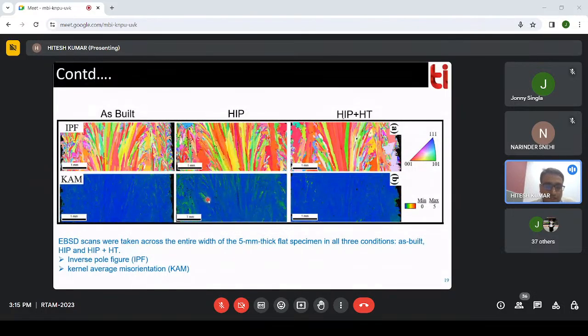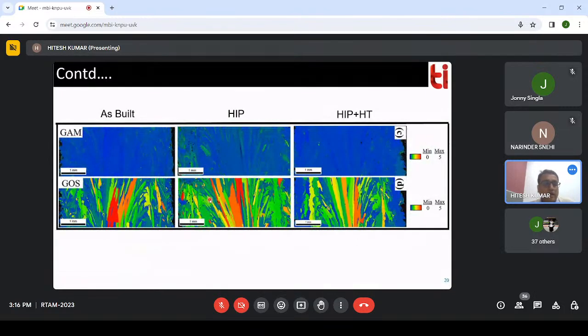So if you can see, there is some misorientation inside your material. This is the best way to find out how much misorientation there is, and with the help of that we later also calculate the dislocation density inside your material. To confirm this part, we also calculate the grain average misorientation of your material.